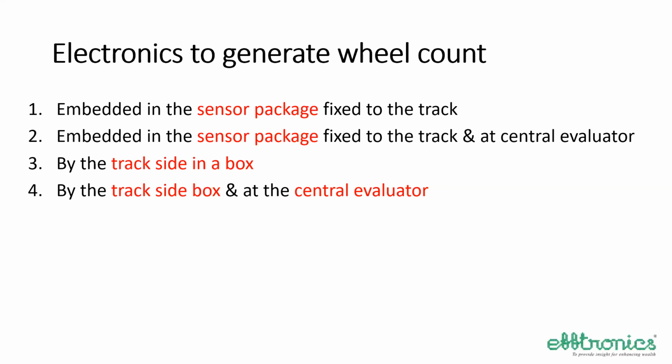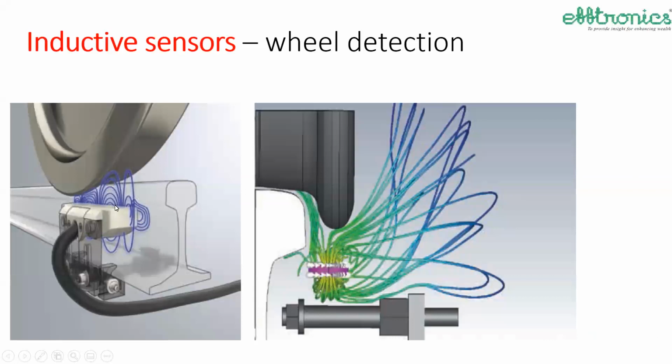So electronics is required at the wheel detection point to generate a count. Now in this, we can't say there is no electronics. The entire electronics is embedded inside: the signal generator, amplifiers, then again, yesterday we have seen the pulse recognition and then counting, including the modem. The whole thing is packed inside. It cannot be said there is no electronics inside. There is electronics inside this.